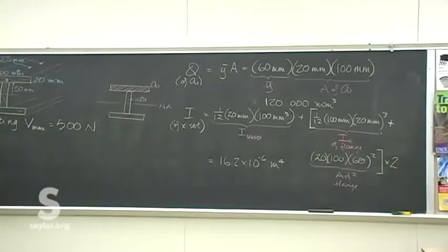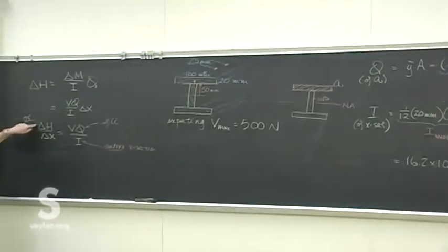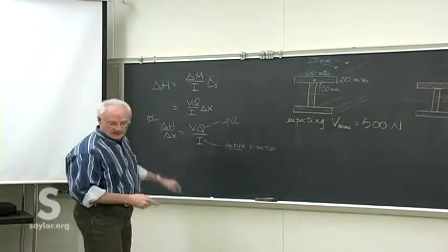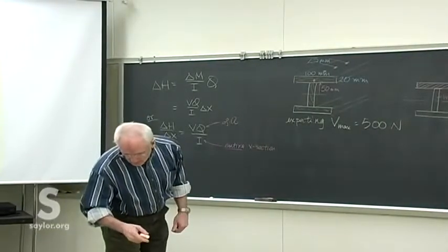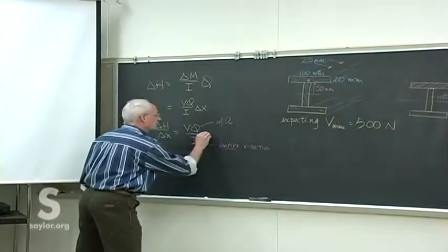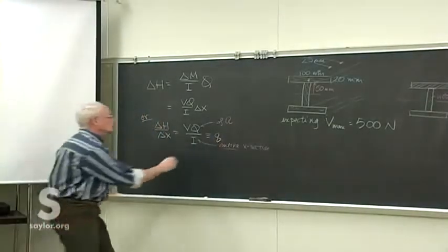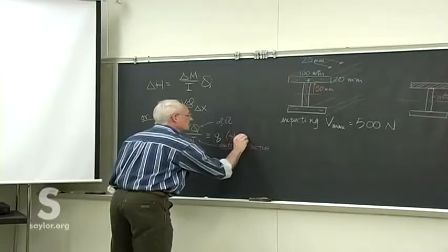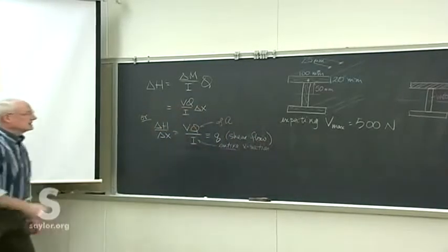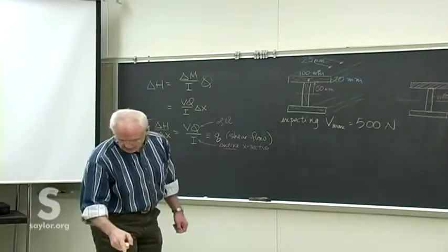So now we have all the pieces. Now we'll be able to find the shear per unit length. Then we'll put in the fact that we have 1 nail. By the way, this is often given the symbol little q, also known as the shear flow, because it's as if that's the amount of shear that's flowing down the cross section there as we look at it.